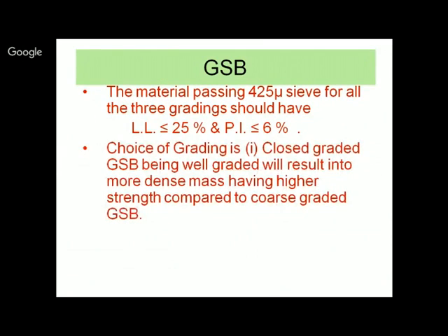Okay, what else? Which one to choose, close graded or coarse graded? Obviously close graded is well graded and will result in a more dense mass, having higher strength compared to coarse graded GSB.